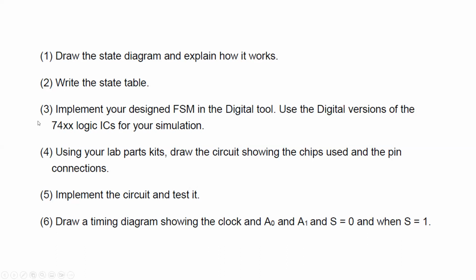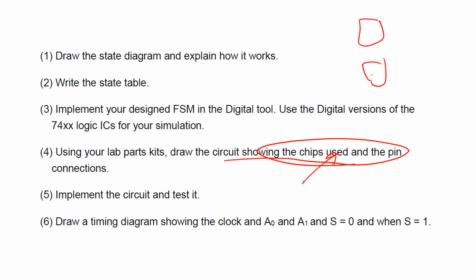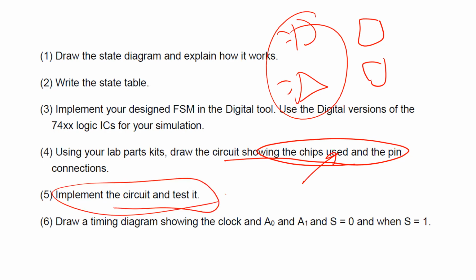After that, I'm asking you to draw the circuit. This circuit should have maybe one chip, because you need only two flip-flops, and the chip already has two. You need to show me the connections. Also, you need to decide whether you are going to use AND or whatever gates, and keep that in mind. You have to implement it, and you also have to test it.